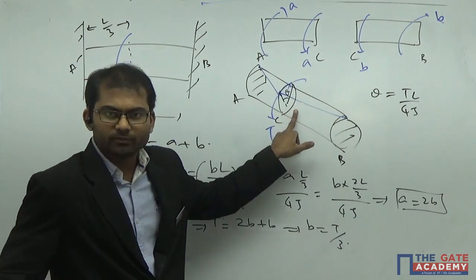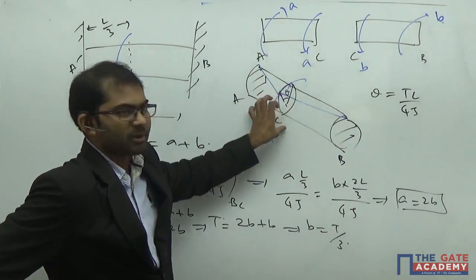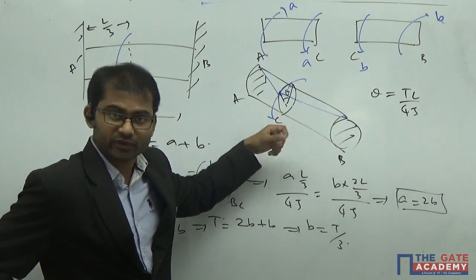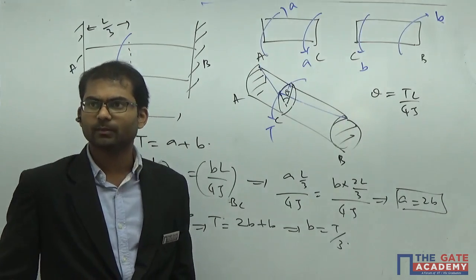See this diagram here. It's a compatible situation. Understand? If a torque is applied here, it will create the same amount of angle of twist in both the sections. That's why we have to take it equal. That's what actually occurs here; I'm not taking some approximation.